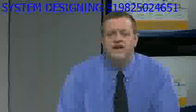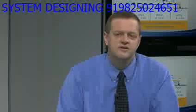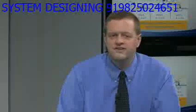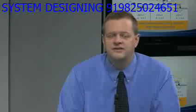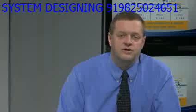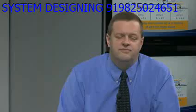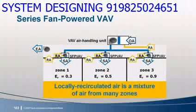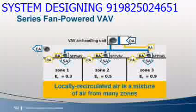Now, Standard 62 does not currently provide a default or calculation method for E sub R, so it's left to the designer's judgment. However, example 6-F in the user's manual provides some guidance based on an ASHRAE research project that measured E sub R in a real building, with fan powered boxes in various locations.